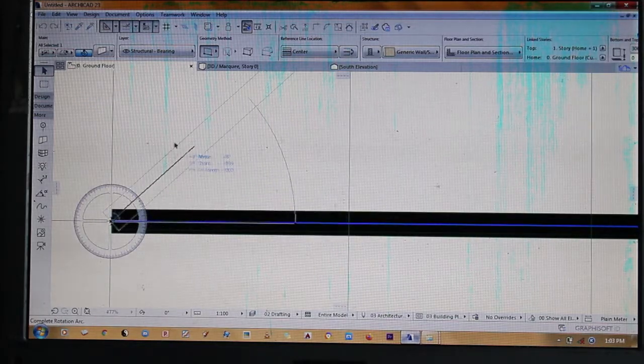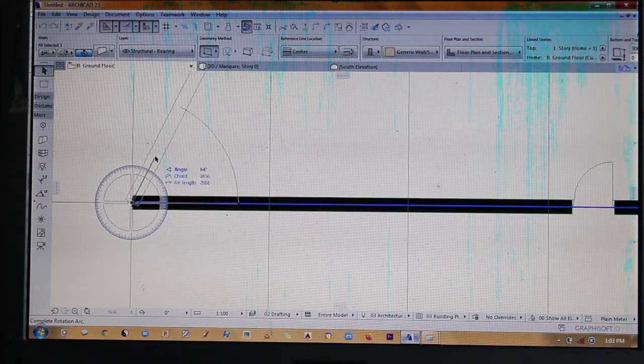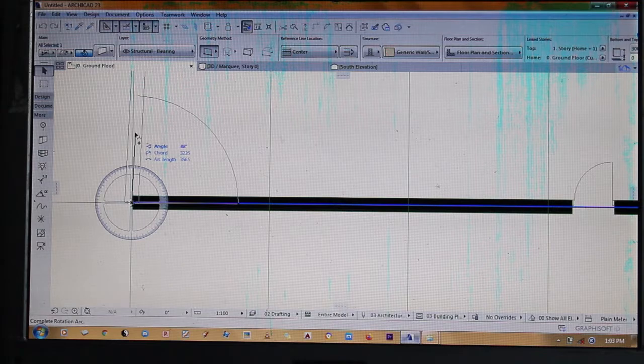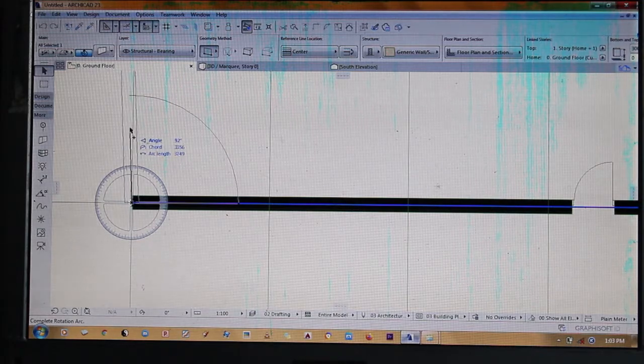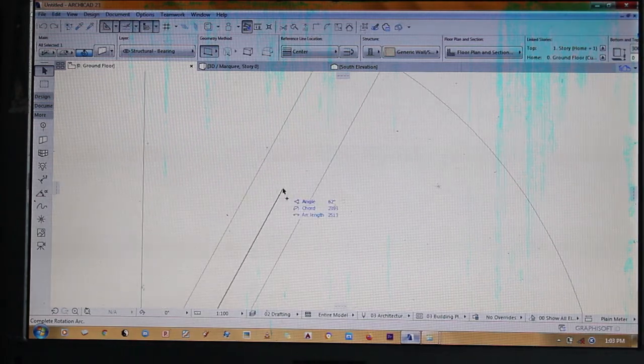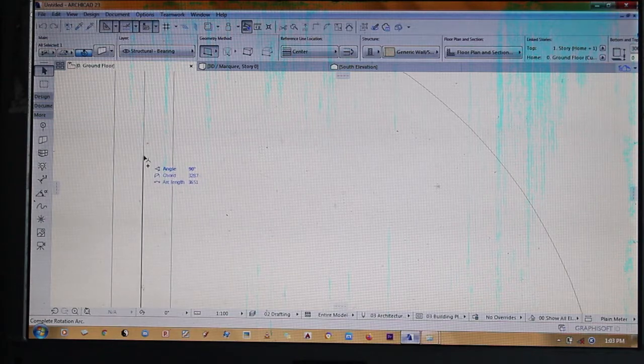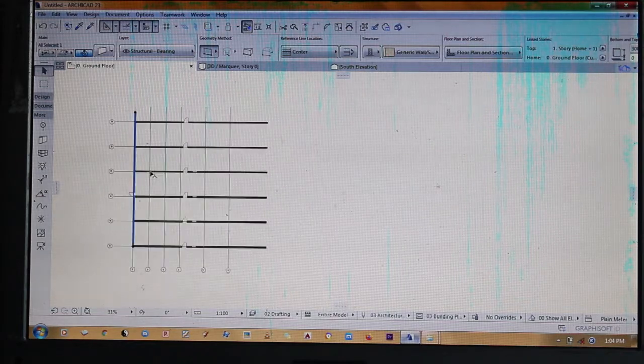If I rotate it, it's going to be rotated as a single part. But if you hold Alt or Control, it's going to be a copy. You can see that plus sign. The plus sign means you are rotating a copy. I don't know if you guys can clearly understand what I'm talking about, but if you are about to rotate, you can rotate a copy by holding Control, and then you hit that copy. So you can clearly see.